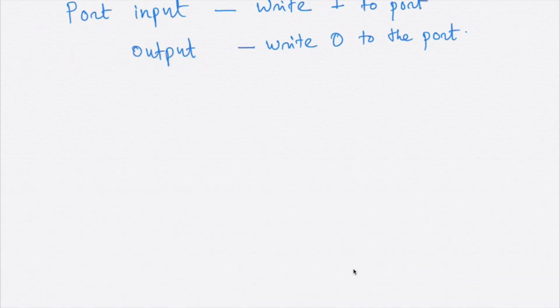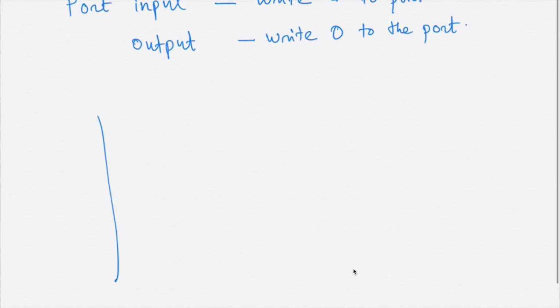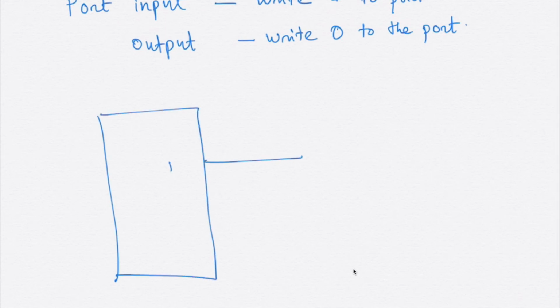For example, in my microcontroller, if I have one pin of port 0, P0.1, inside the microcontroller I have sent FF, so I made P0.1 equal to 1, so we configured it as an input port. But since this port is connected to some external device, let us take an example: this external device is a switch or something.